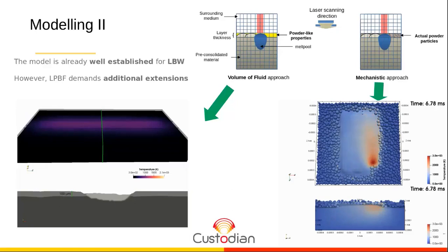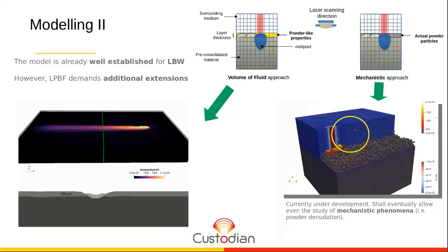But the simulation actually took longer because we had to generate the powder bed with Lagrangian particles that are meshless methods, so they're like single particles, and we had to couple both approaches, Lagrangian and Eulerian, for mass transition and energy transition and momentum exchange during the whole process.